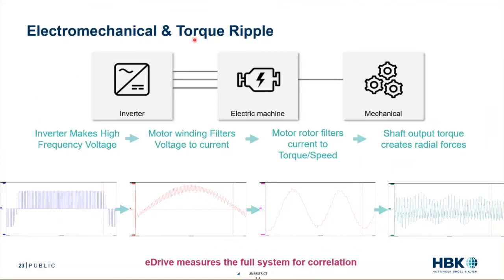We are electromechanical, and this doesn't show up as good as I hoped. I'm sorry about that, but we will record your high frequency inverter at a high enough rate where you can understand all those PWM switches. We'll then record the current at that high rate so you can see the current harmonics and start to tie that back to maybe torque ripple or vibration.